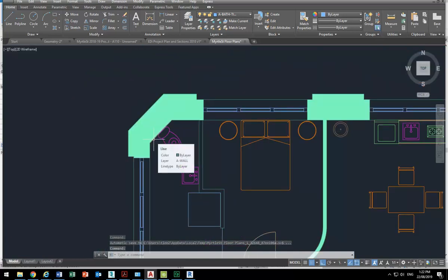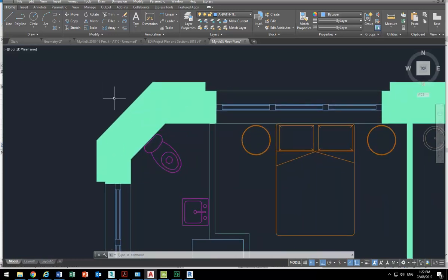What's the size of the riser? Well, you can look it up, and you should really have a go at looking up the size for those things, but also just have a look at some toilets and measure the pipe, or even just eyeball and see how big you think it is. You'll see they're about, well, it used to be 8 inches or 6 inches, but in metric, so around 120 to 150 mil. Yeah, so about this big.